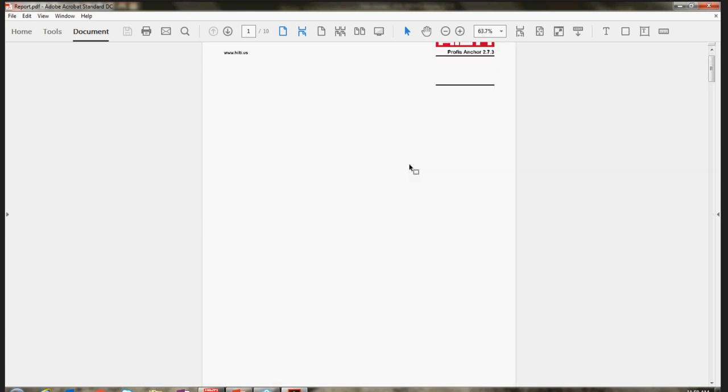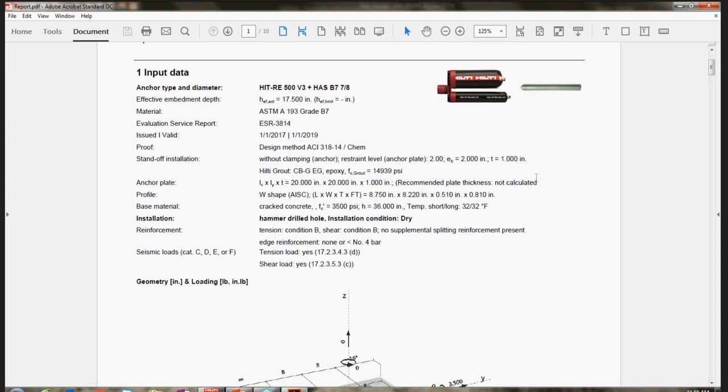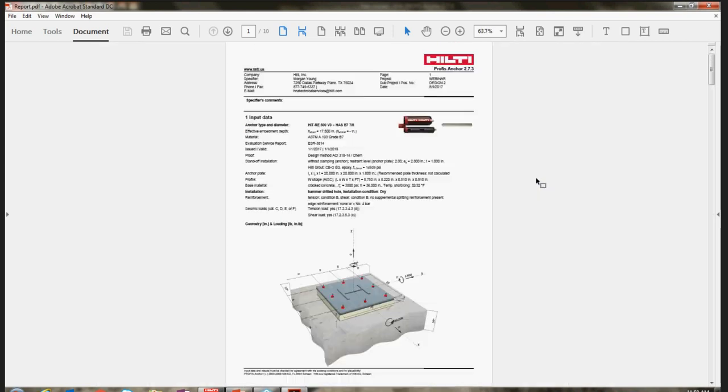We're going to take a look at a W8 by 58 flange. You'll note when I select something, it's highlighted orange. That means it's activated. So I'm okay here. Everything looks good, except I want to rotate this profile. So I'm able to do that by the rotation, and if I wanted to change the eccentricity, I would be able to do so.